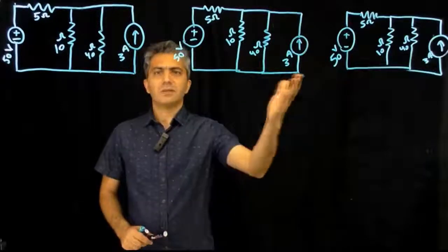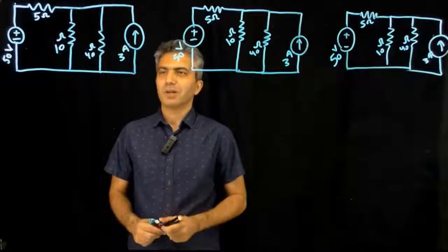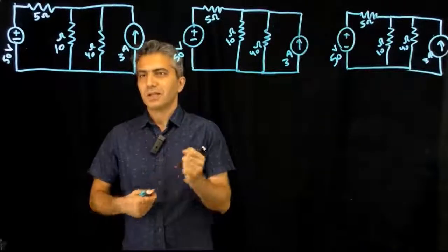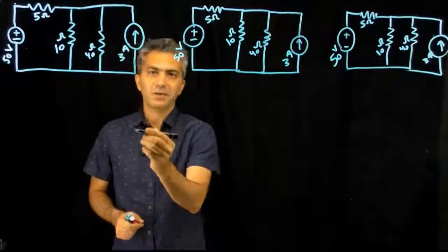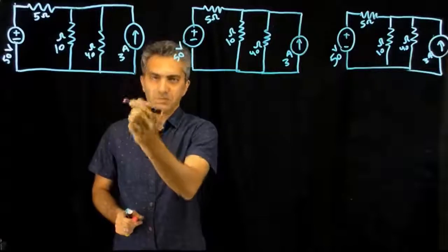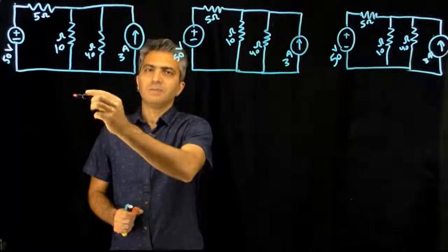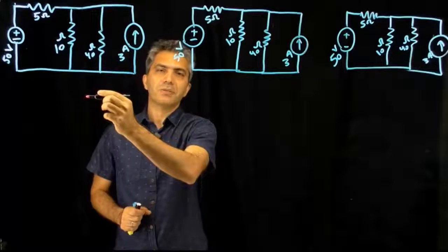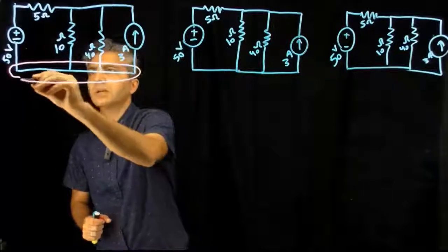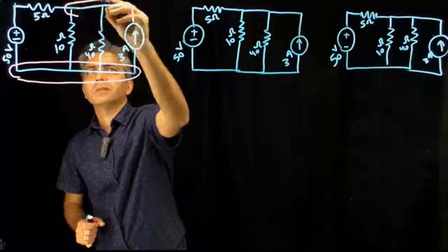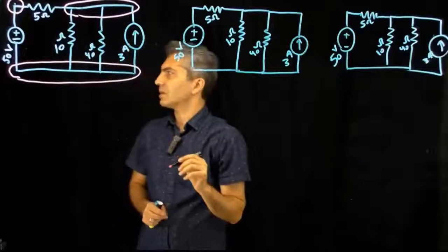Okay, so this is the circuit that we're going to analyze. I'm going to start, obviously, using our beloved technique, the universal technique. So we first label the circuit. We're going to identify all the nodes and label them with voltage variables, and then define currents that are passing through the components. So this would be one node, and this would be another node, and it would be another node, and that concludes the nodes in the circuit.